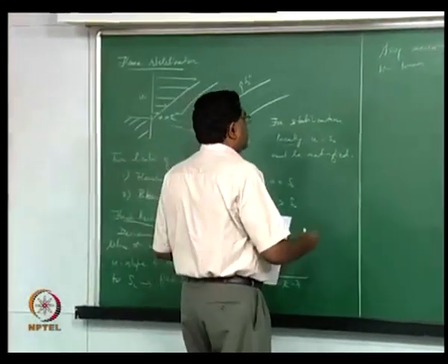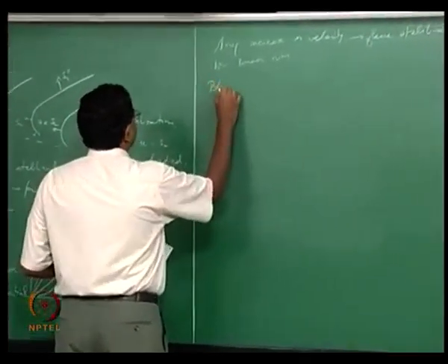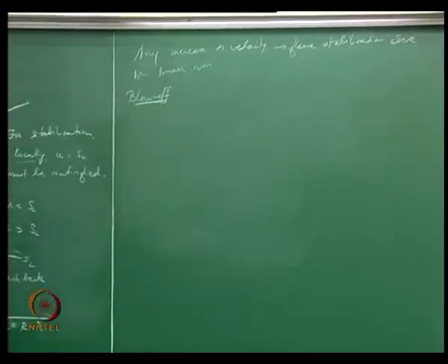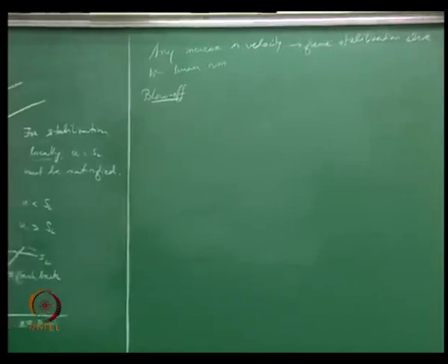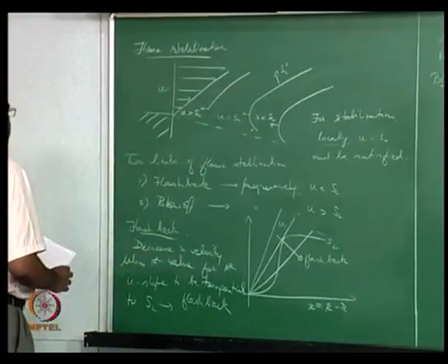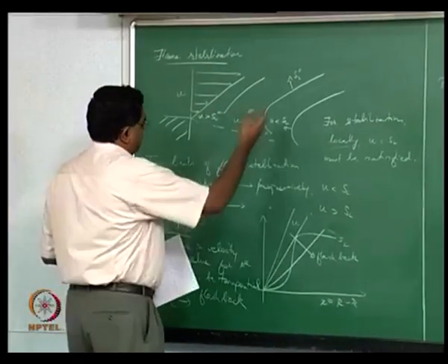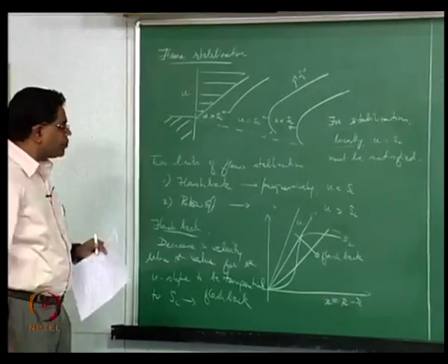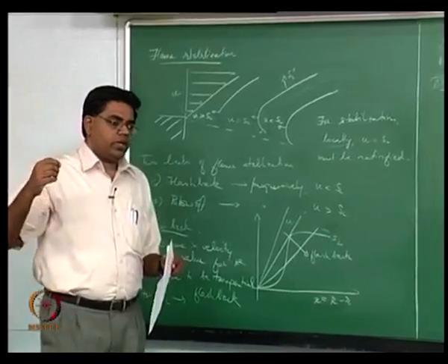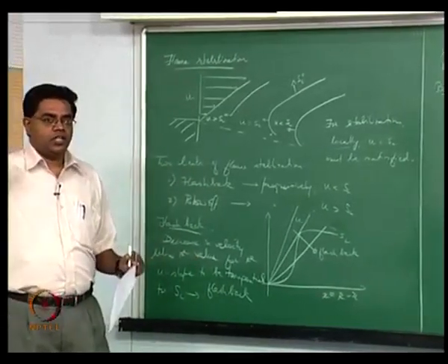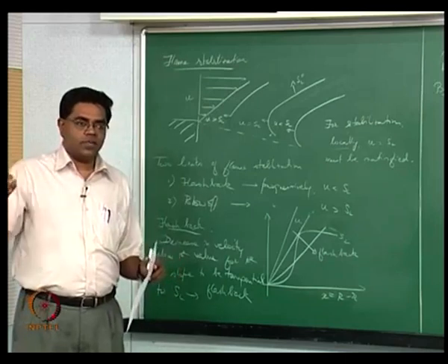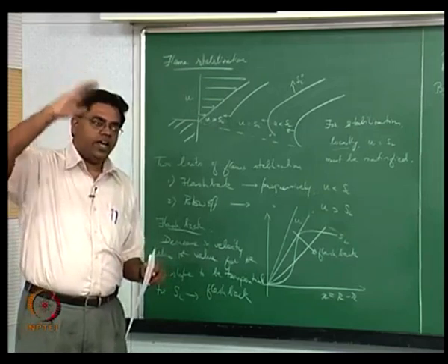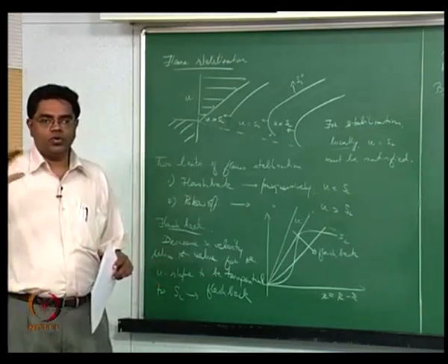Then what happens if you keep on increasing the velocity further and further, right? We have seen what is likely to happen, that is, the flame shapes itself in a way to adjust to the increasing velocity situation. Alright, we have found that with an artificially simplified condition that zeta is equal to 0 at r equals capital R, you could say that the flame is going to be a conical shape of any angle depending upon the SL over u ratio.